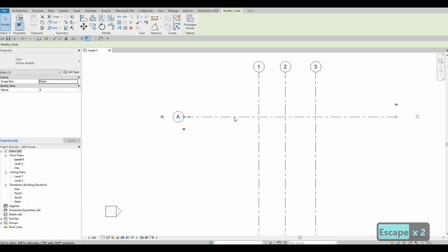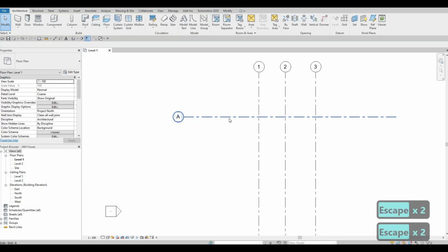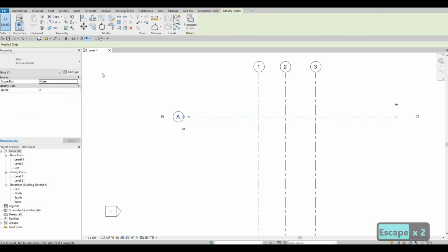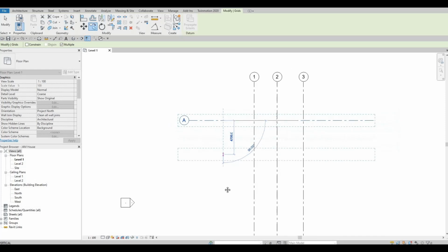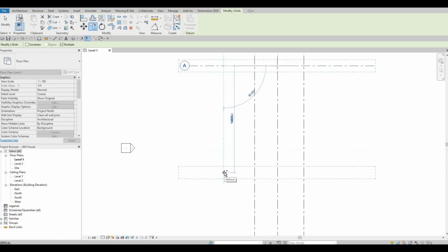Now I'm going to press Escape. Again, I'm going to select that and then type in CO. Multiple is already checked, because from the default we checked Multiple and it will recognize it again. Every time you copy now, just double check, but I'm sure that it will stick with Multiple checked. Now I'm going to grab it and pull it downwards on my screen.